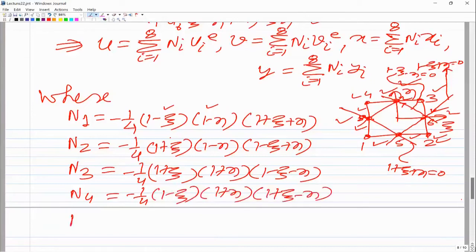For n5, keep in mind that this is different from an 8-noded 3D element. An 8-noded 3D element is an element in 3-dimensional space. Now we are talking about an element in 2-dimensional space, where, for the plane stress, plane strain, and axisymmetric problem, there are two unknown displacements u and v, but there are 8 nodes, and all these things are functions of only two coordinates, xi and eta, and the physical coordinates are functions of only x and y. So this difference you should keep in mind.